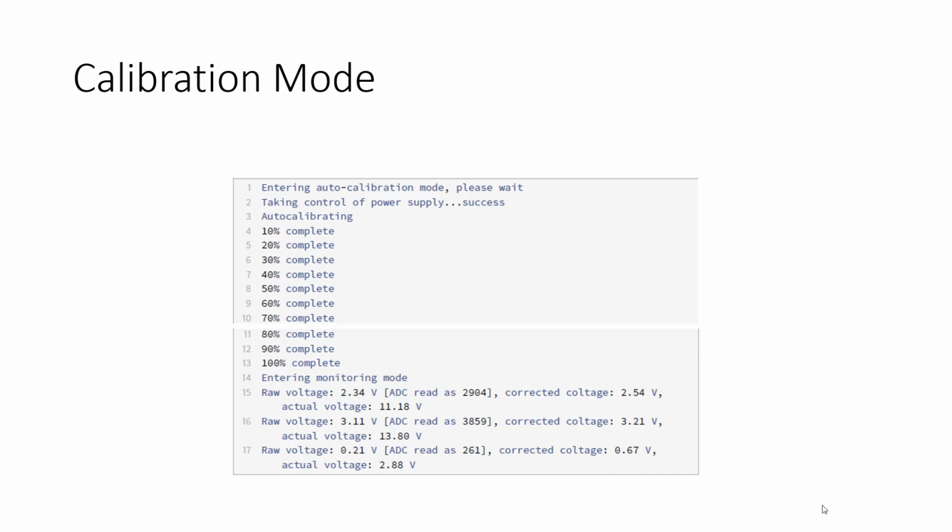So just be careful where you plug the power supply and don't go over 12.6 or 14 or whatever. 14, I think. Yeah, don't crank it. Remember, the power supplies go up to 30, so you can easily blow these things, okay?